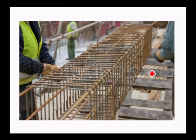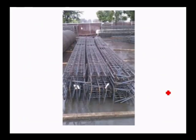After tying at the side, then they will erect it in the field at the actual position, centering it depending upon the grid how they are marked. This is the cages. Like this, if there are n number of columns, all the columns will be tied in one place, and then they will be transported to the field.